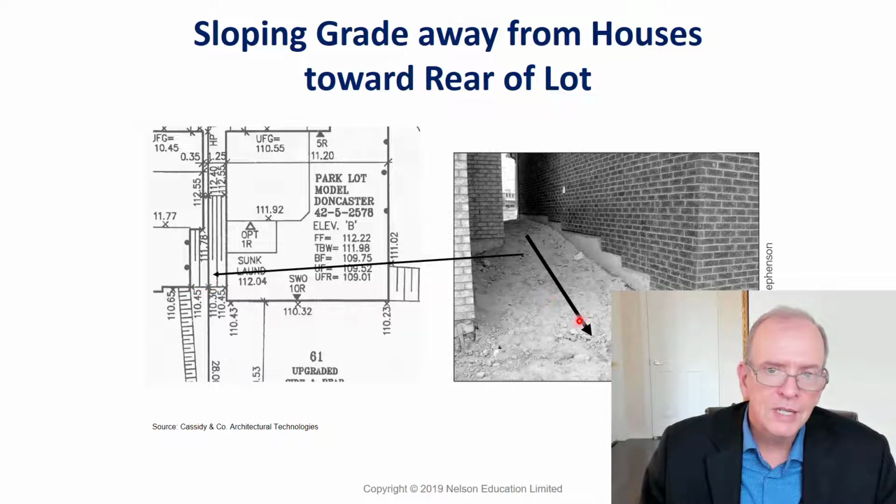So that means this is up 6 inches, and when this is finished, this should be up 6 inches. So the water goes down the middle, and then it runs that direction, right? So at the high point over here, we've got 112.4, and at the low point here, we've got 110.3. So that's going to slope, and any water that's gathering here is going to build up and run off.